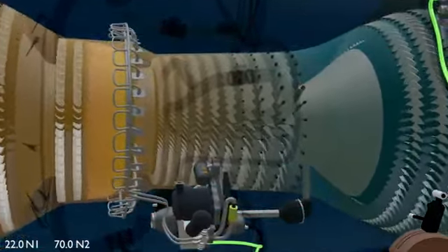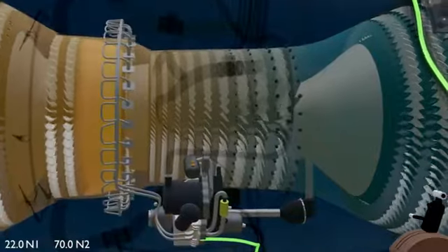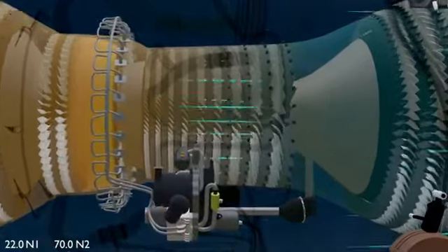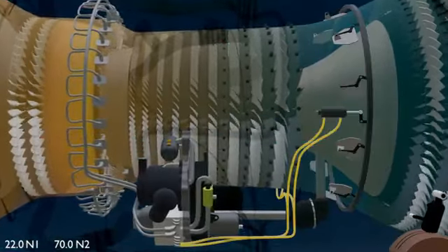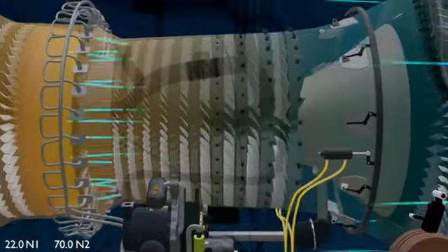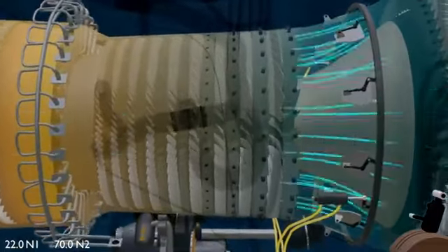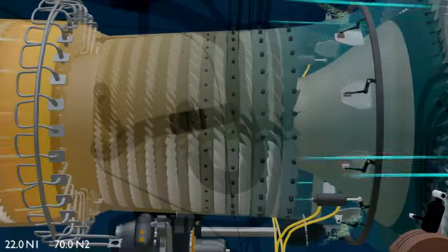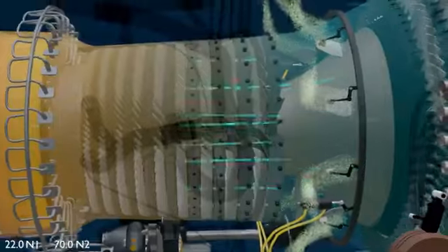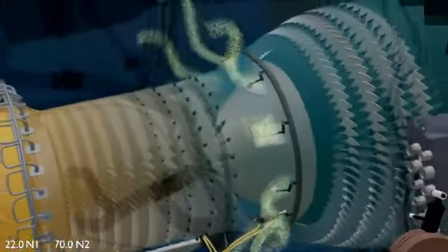The HMU, apart from controlling the fuel for combustion, also controls the servo fuel system of the engine. It uses servo fuel pressure to operate the 2 VBV actuators. The actuators, with the help of bell crank and unison ring, control the 10 bleed valves located behind the LPC casing. The valves now open to let part of the LPC exit airflow pass through ducts and into the engine bypass airstream. This helps to match the LPC exit flow to the HPC intake, thereby reducing the load on the low-pressure compressors.